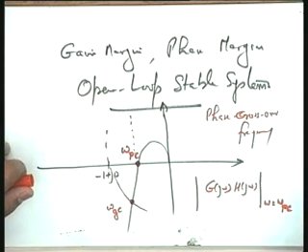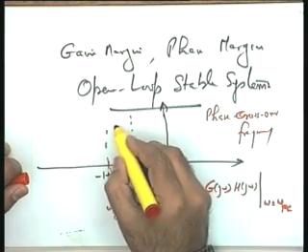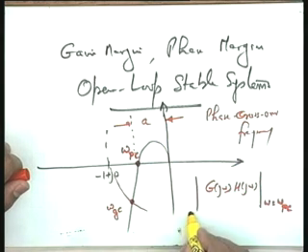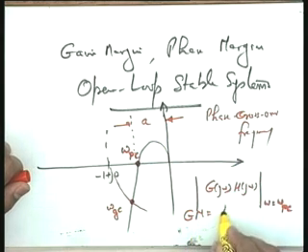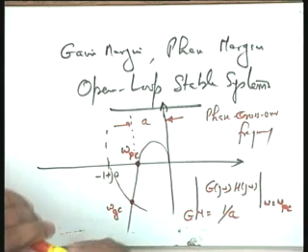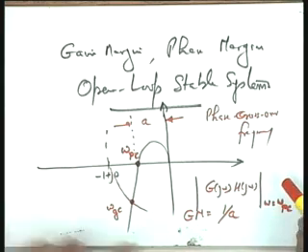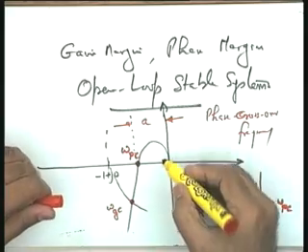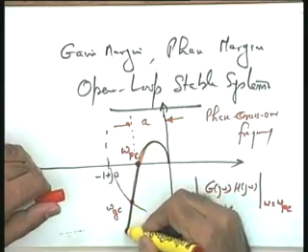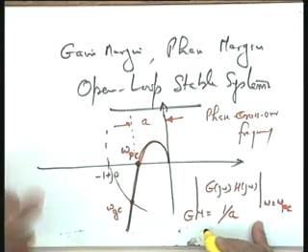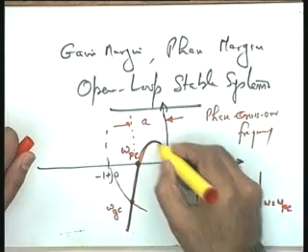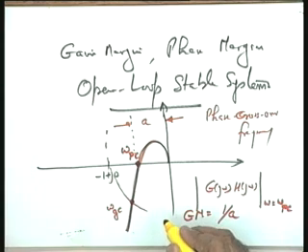Analytically also you can obtain the gain margin and phase margin. Please see, at this particular frequency take the magnitude and say that this magnitude is A. In that case your gain margin is equal to 1 by A. Okay. So, this is the gain margin, relative to the original gain of the system for which this plot has been made. This point may please be noted, it is not the gain of the system, it becomes the gain only when the original plot has been made for a unity gain.